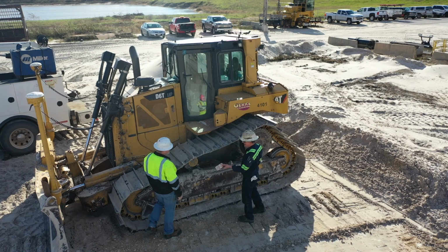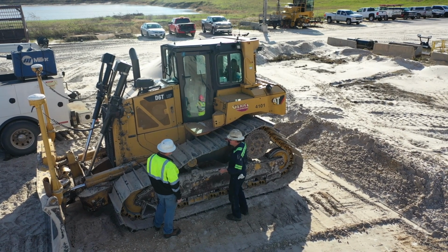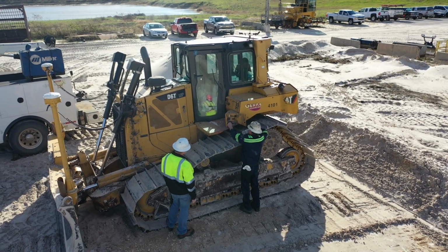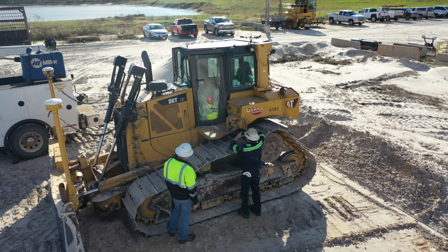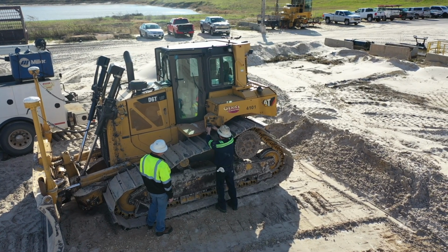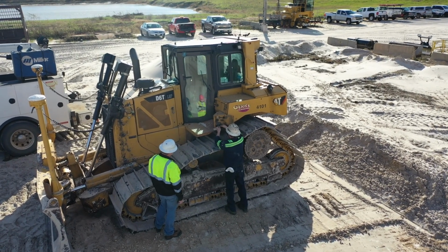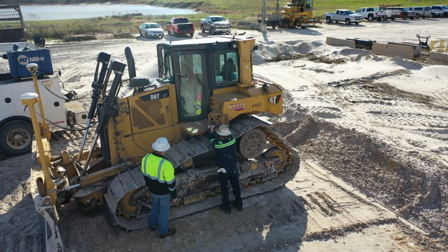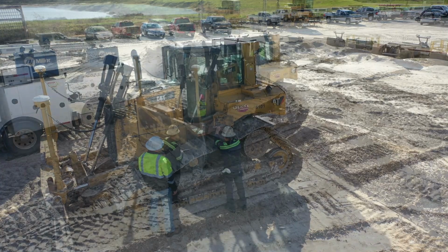When working under or around bulldozers, for maintenance inspections or repairs, the bulldozer must be locked and tagged out, and immobilized and secured against inadvertent movement. Lockout procedures must be followed during mechanical service, repairs, or inspection for the protection of employees and equipment.